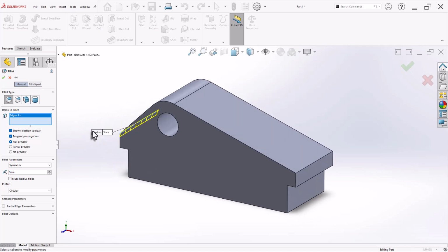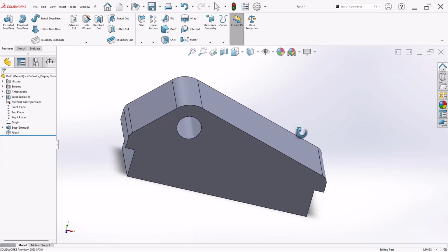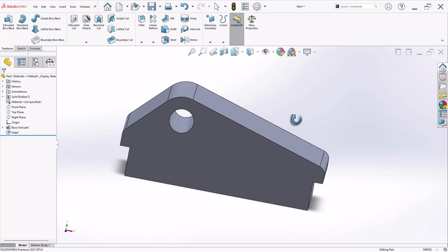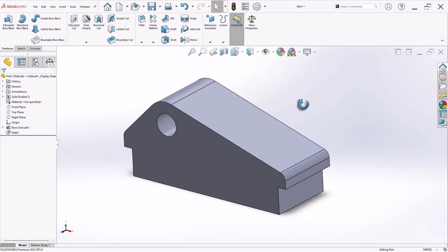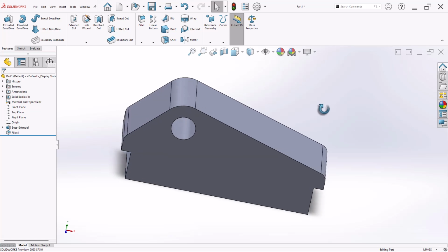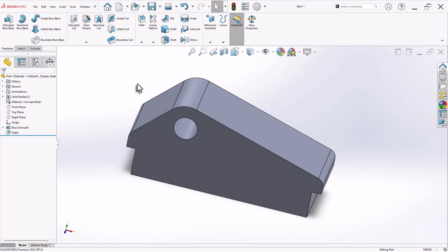The reason why I use a fillet feature, especially in this exercise: if I use the sketch fillet, the answer differs. That's why I choose fillet features. I also recommend that you avoid filleting in the sketch. Better you use the fillet feature separately to get an accurate answer.